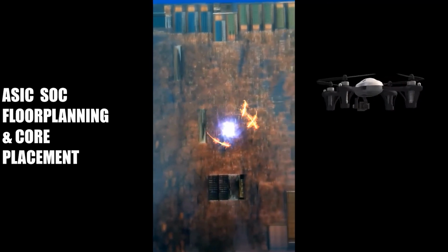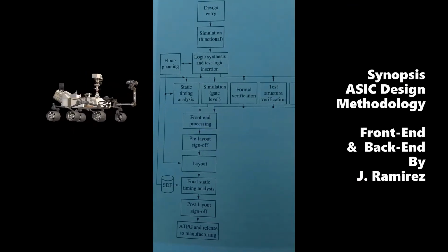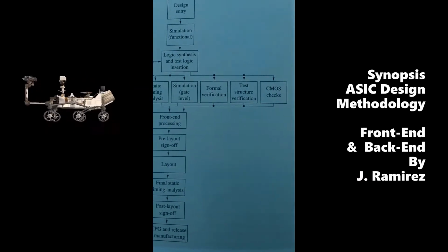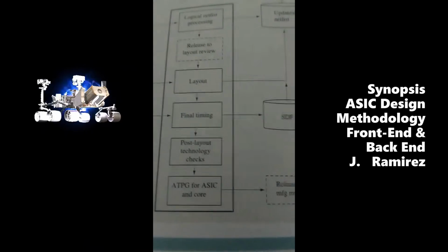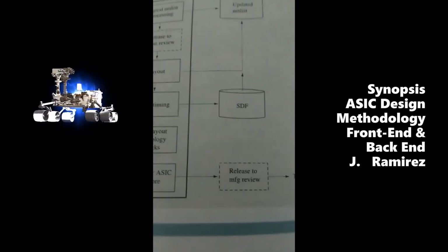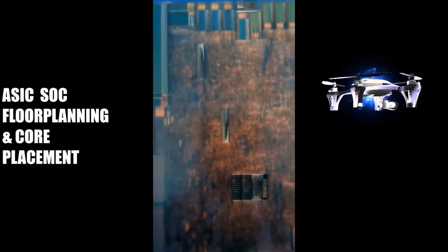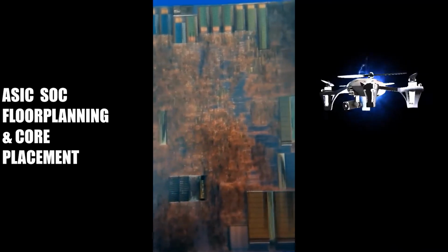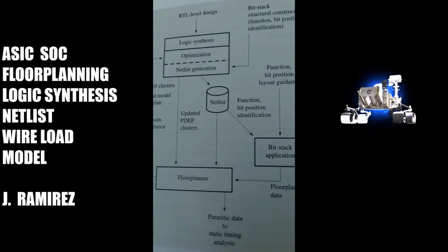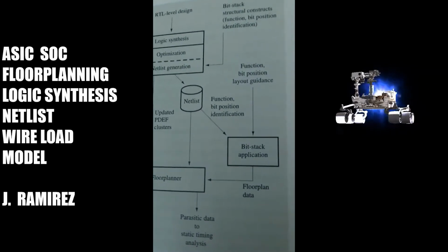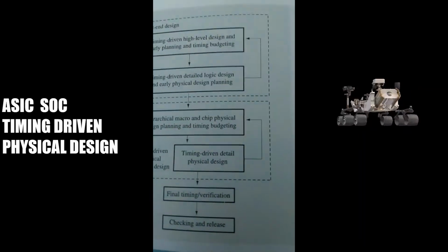which consists of design entry, simulation, functional simulation, logic synthesis and test logic insertion, static timing analysis, simulation, gate level, formal verification, test structure verification, CMOS checks, floor planning, front-end processing, pre-layout, layout, final static timing analysis, post-layout, and ATPG and release to manufacturing.